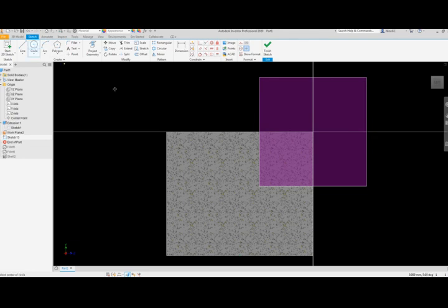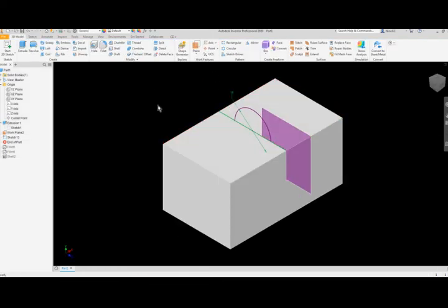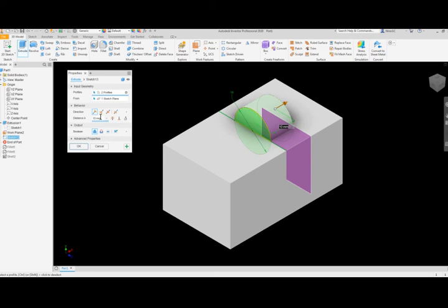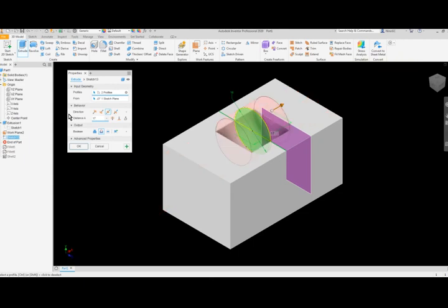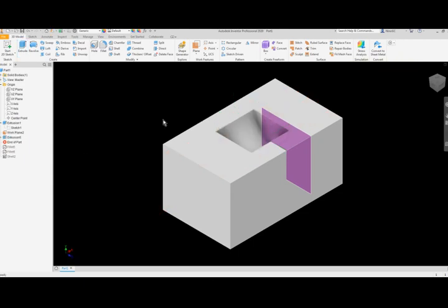By doing it that way, I can now input, say, a circle. I'll give it an actual size of 16. I'm going to finish my sketch, and we can see where that sketch is actually located. This allows me then to create, say, a trough, which is midway, and I can extend it as required. So I'll just extend this to, say, 17. So 17 millimeters. Click OK, and now I have that.